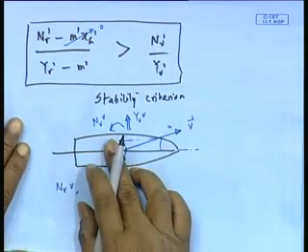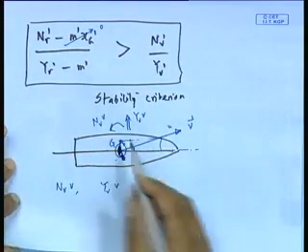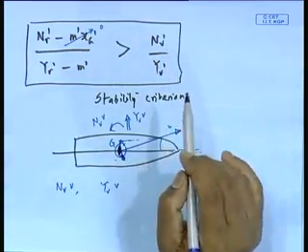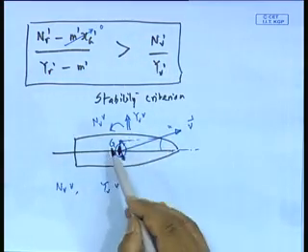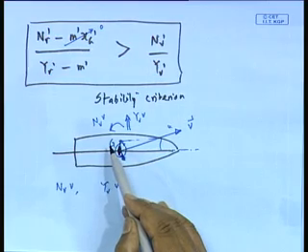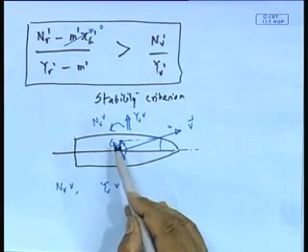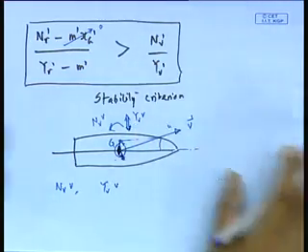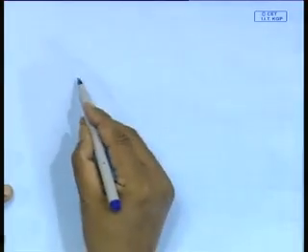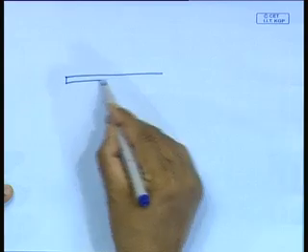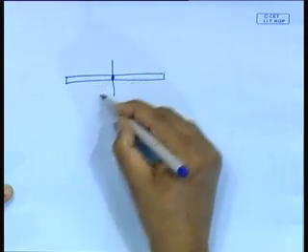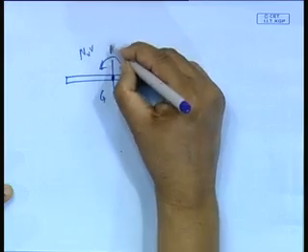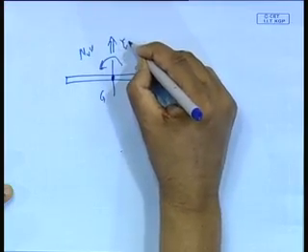Now, you see here what is happening. For this hull, if I give a V, Nv and Yv tell me that I get a moment NvV, right, and I get a force, it can be in the other direction, whatever the diagram shows. So, my point is that if I draw a stick-like ship here, with G here, I am getting an NvV here and a YvV here, whichever way.